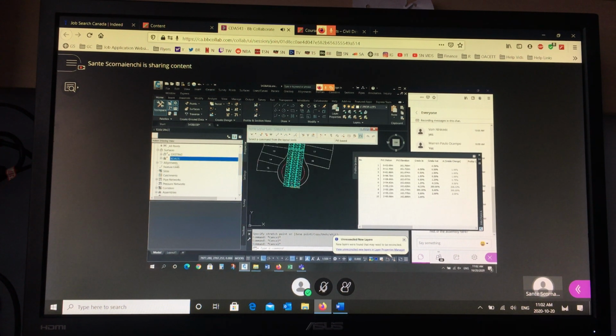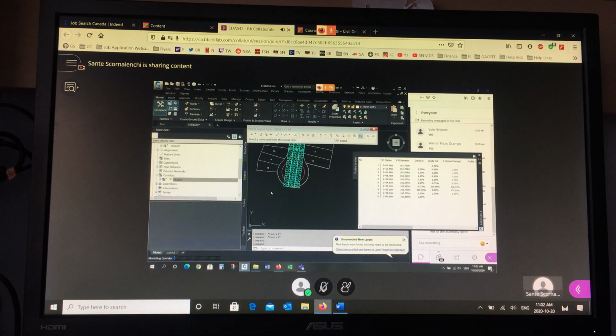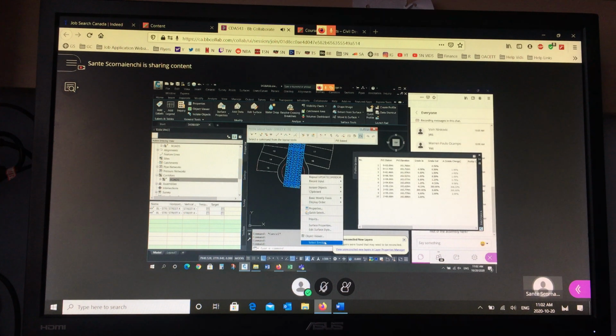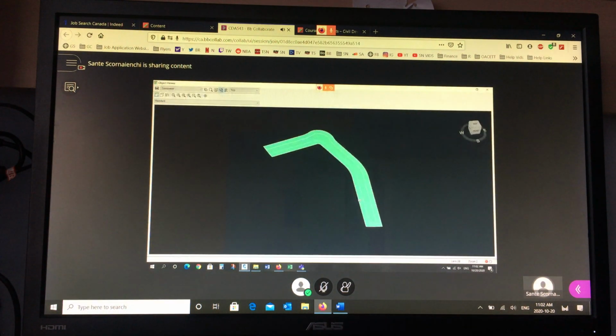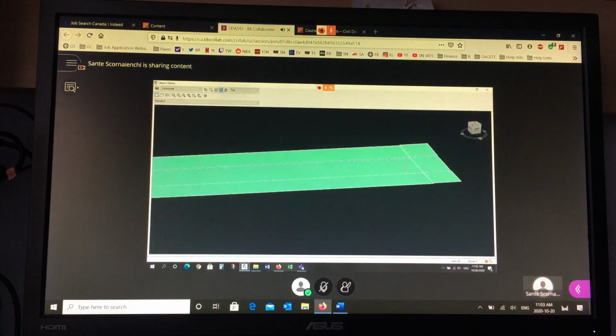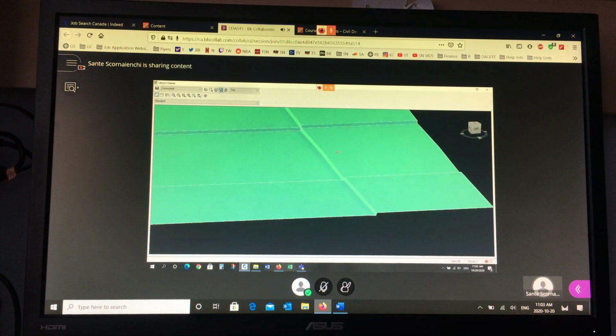If you rebuild the corridor, if you ever get that little shield, that warning, you just rebuild it or set it to automatic. It rebuilds, and that should get rid of the spike at the end now, because now there's more profile. Object viewer, and you'll see that it's gone, and if you zoom in, it's going to look kind of funny, but it'll look like a curb and gutter. You see that? It's kind of silly right here, but that's what it is.